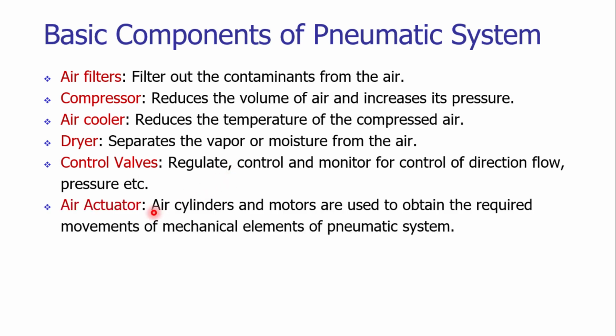of the compressed air. Air actuators are basically cylinders, double acting cylinders or single acting cylinders, or we can have pneumatic motors as well, which are converting the pneumatic energy, pneumatic force into rotational energy, and that rotational energy would be used for a variety of applications. The pneumatic cylinders and pneumatic motors are used to obtain the required movements of mechanical elements.